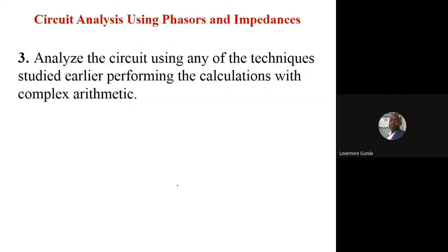Then you analyze the circuit using any of the techniques that we studied, performing calculations with complex arithmetic. So what I'm saying is in AC, you are dealing with vectors, which have magnitude and direction. The same way you add your vectors is the same way you add your impedances.